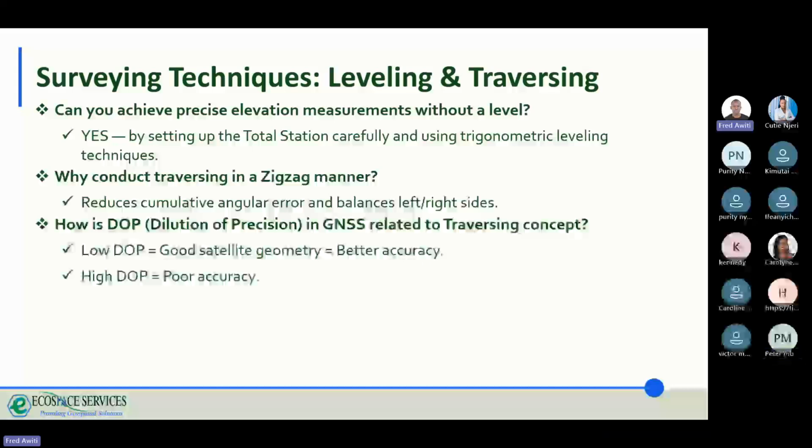Remember, we have L1 as a type of frequency. We have L2, L2C. So you find that one satellite can give you different kinds of corrections. These corrections have a purpose. One can penetrate. That's why there's a certain receiver that, if you use it, can work better under a canopy, but another one cannot work under a canopy. Then comes the issue of having a receiver that can tilt, while another one cannot tilt.